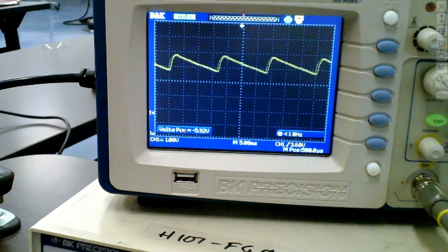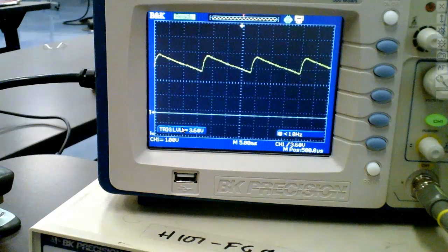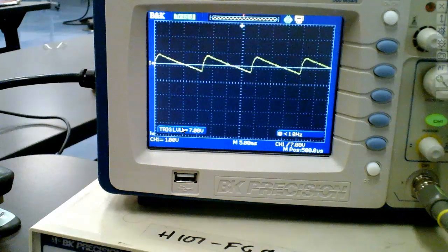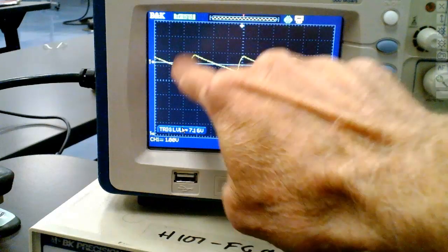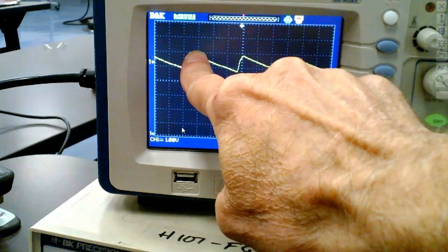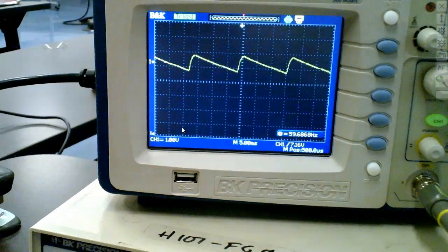So all we're doing now is looking at the ripple. You can actually see it charge the capacitor. Right here, the capacitor charges. Well, then as it goes down, the diode is reverse biased, right? You understand? Because now we got it charged up, so the diode cuts off. And what's happening now is the capacitor's running the load until when? Until the next alternation.